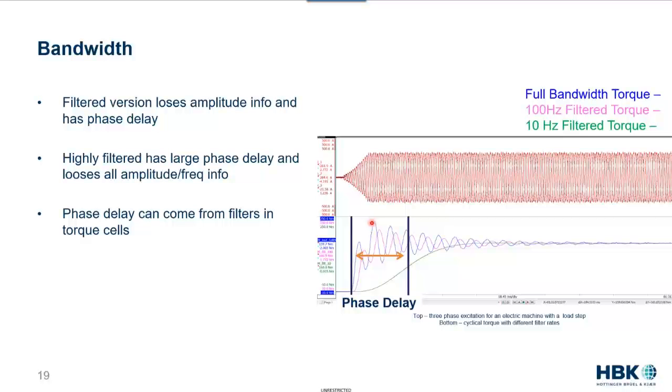And as I mentioned earlier, knowing that maximum torque value can be really important to choosing the components of your system, making sure they're going to be able to withstand those high torque pulses, even if they're experienced very briefly, and also for understanding and predicting the lifetime of the components in the system. What kind of information is that component going to feel and be able to experience, and how long will it last with that high torque value applied?